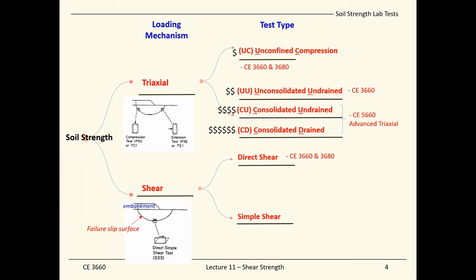And the advanced version of the direct shear test is the simple shear test. The simple shear test allows simulations of earthquake engineering. The cyclic version of the simple shear test is the best to model upward propagating shear waves in the lab, which means it's very ideal to mimic soil elements under earthquake loadings.